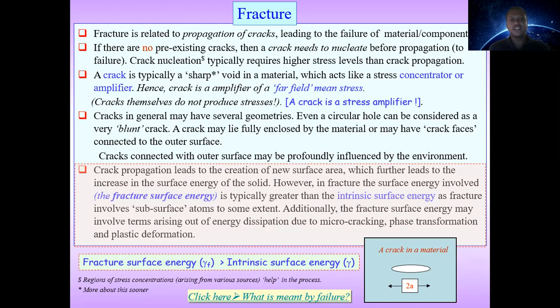the propagation will need less energy. A crack is typically a sharp void in a material, which acts like a stress concentration or a stress amplifier. Hence, a crack is an amplifier of far-field mean stress. Cracks themselves do not produce stress, but a crack amplifies the stress.